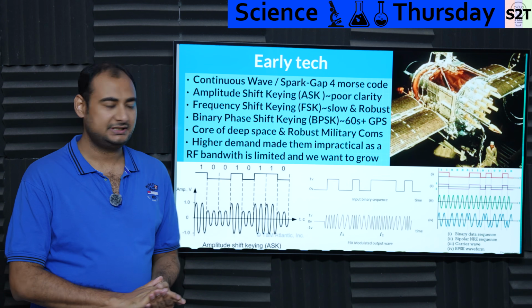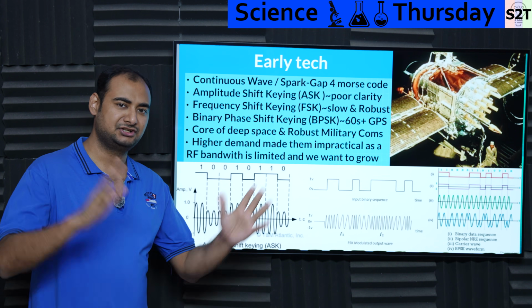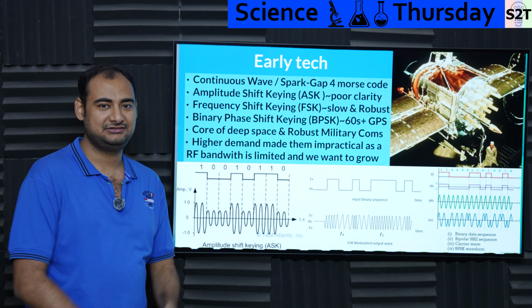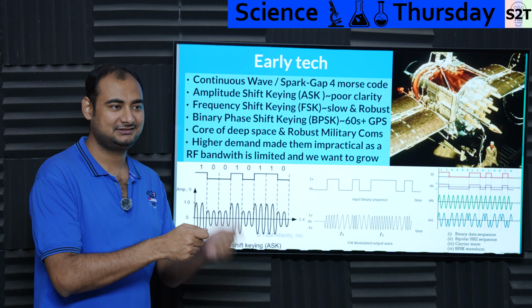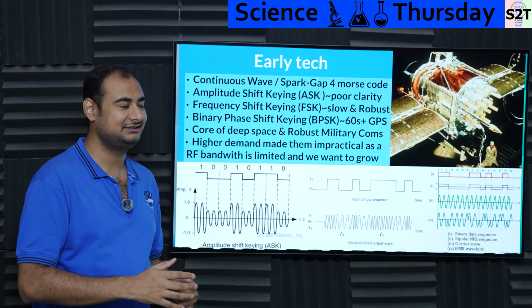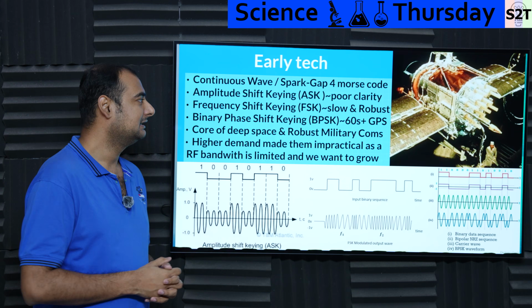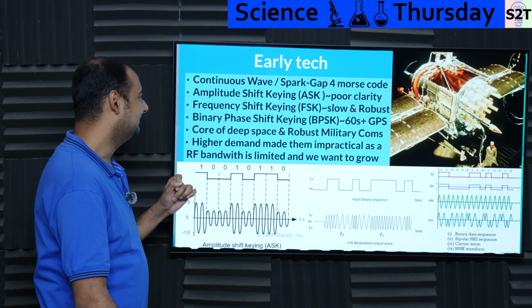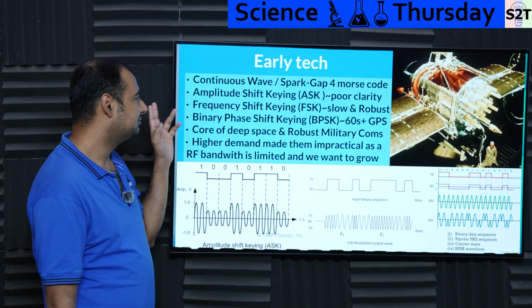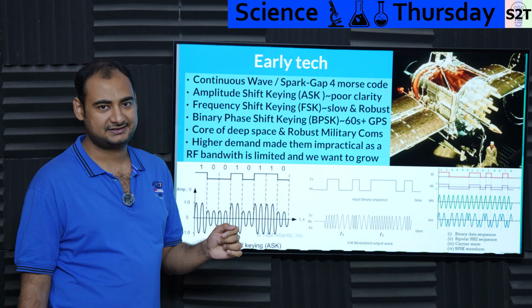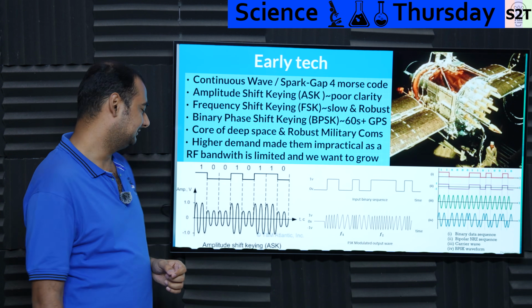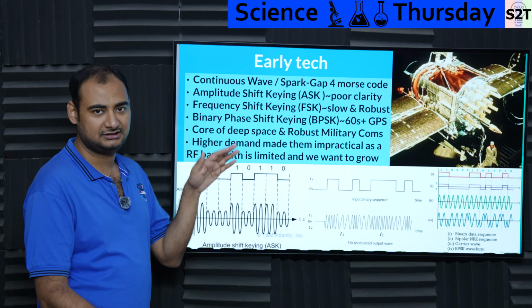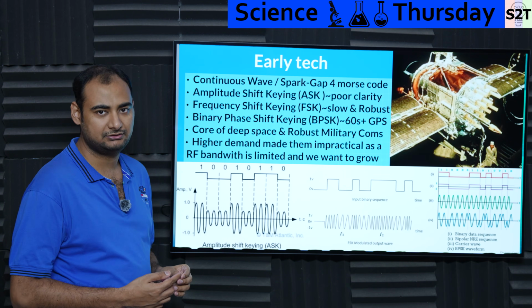Now, early technology: we started with the ancient era. Before we had AM or FM, it was a continuous wave spark gap. Basically, we had T, T, T, T, very old school. Morse code. Morse code is fundamentally digital. That's how we started. And then we went to amplitude shift keying, ASK. This was very short-lived, because the idea was, what if we had a loud signal for, let's say, 1 and a small signal for 0.